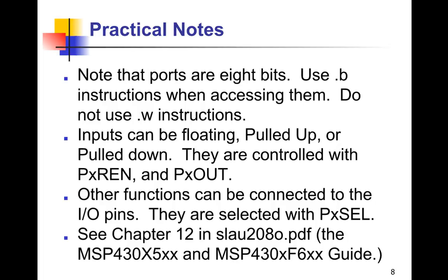Other functions can be connected to the I/O pins, and so some chips have more than just GPIO on some ports. Like there might be a timer or some other things, and you'd use the PX or whatever the SEL register, the P whatever SEL register, to select those other special peripherals that are more complicated than general purpose input output.